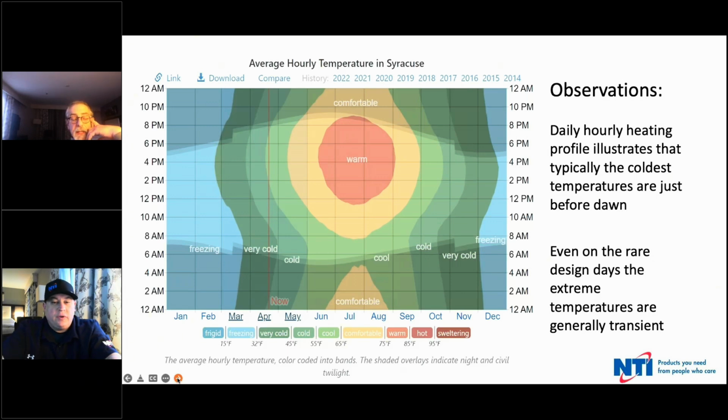And then we add boost function. Yeah, well, that's another thing entirely, where we take the reset and we actually play with it to increase the output if the boiler doesn't sense a temperature rise in the return.